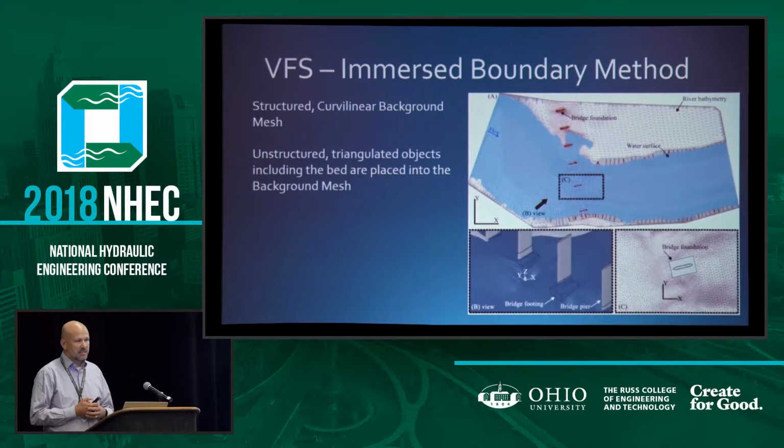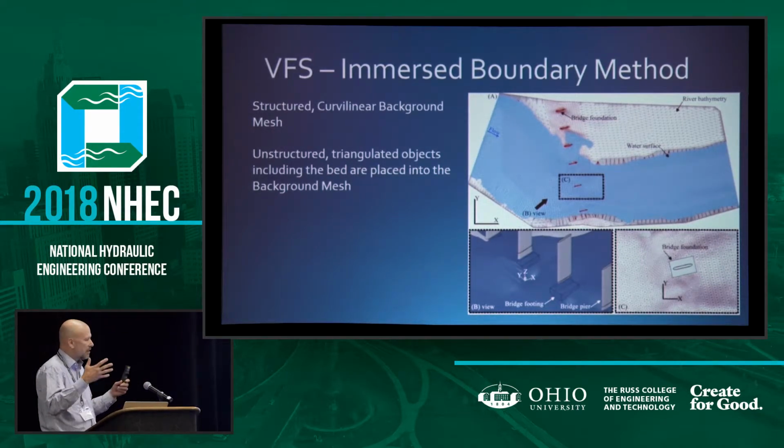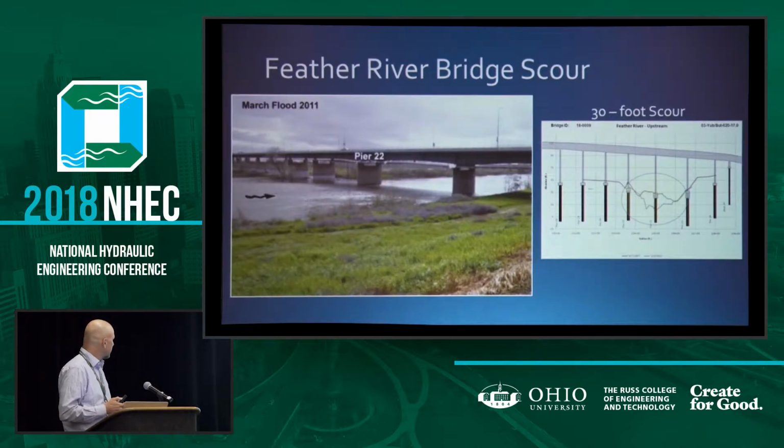It's the idea that instead of developing a mesh that's really refined around all your objects, you create basically a structured mesh, a curvilinear structured mesh, and then you can just stick objects into that mesh, and then the code itself will define where those boundaries are, which at least had the appeal of being maybe a much simpler way to deal with the meshing, as well as maybe a way of solving some of the sediment transport issues as well. So those were some of the main reasons for it.